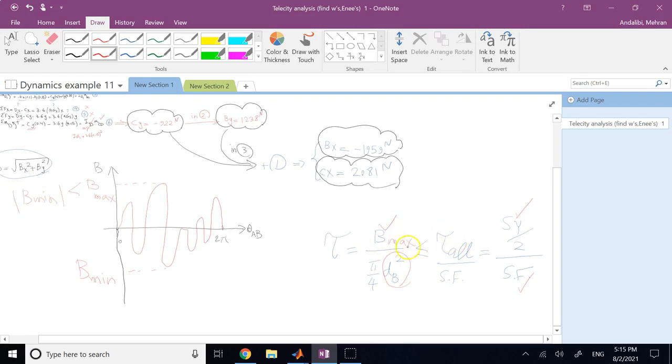So find what is the maximum load during one full cycle by repeating these calculations over and over for so many different angles, let's say at least 360 angles. So for each 1 degree, you calculate this one more time. Find B max, choose your material, see how much safety factor your application allows, and then find the desired size of the pin. If you do it, what?